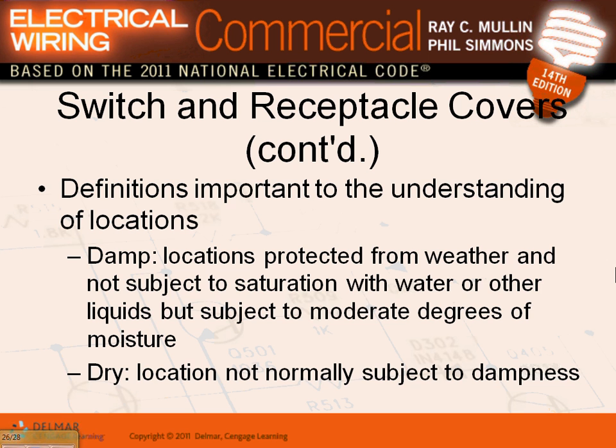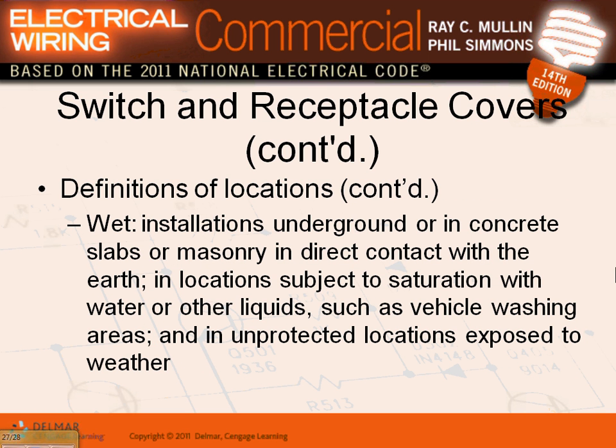Wet location, saturation of water. Wet location, my favorite is wet location. Look at the installation underground or in concrete slabs or masonry in direct contact with the earth, in locations subject to saturation with water, like where you wash your car, or in other liquids such as vehicle washing areas, and in unprotected locations exposed to the weather. These are very clear about where the wet location is. Exposed to the weather, saturation of water, a car washing place, or in direct contact with Mother Earth through concrete or non-concrete. That's a wet location.